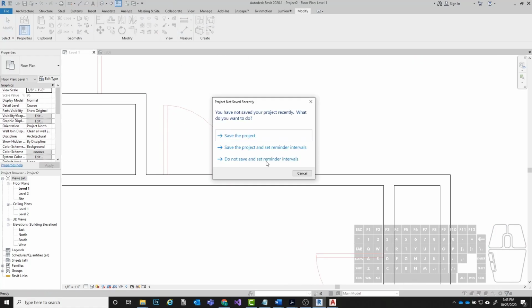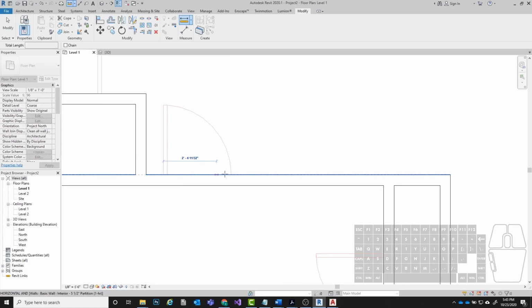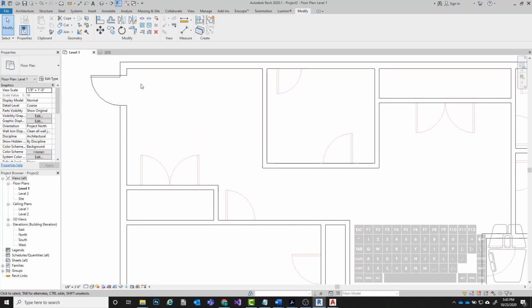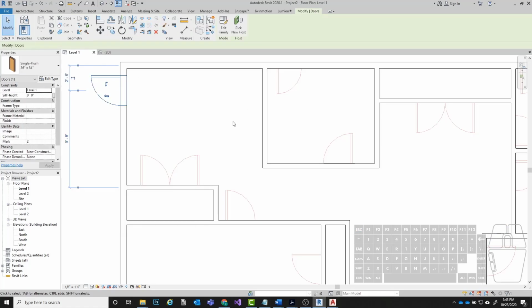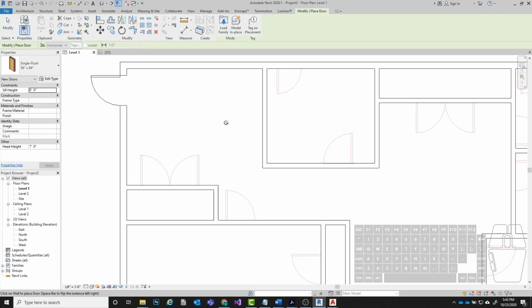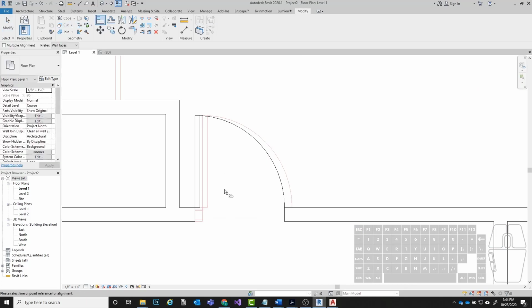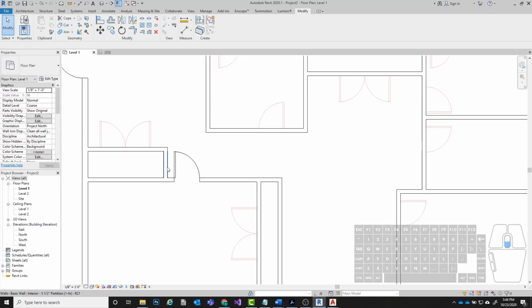This one is going to be also a 3 foot door. Something that we can do is we can actually right click on this door. No, it's not right click. If we select a door and we use the command CS, so CS, that is short for create similar. All right, that is going to basically make a new object that's exactly like the object we have selected. So that's one way you can do it. And I'm going to get this one close to where it needs to go out, and then align to get this in the right spot.